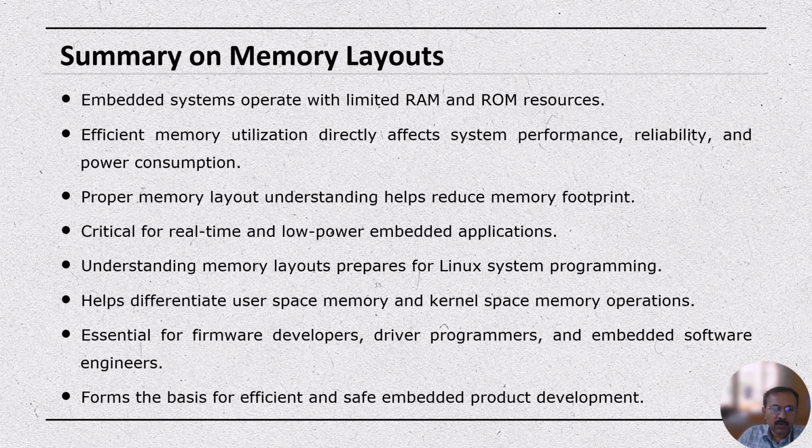It also reduces the memory footprint. What is the footprint? The footprint refers to the amount of RAM and ROM we use for an embedded application. That defines your memory footprint, and it is significantly reduced when you use a proper memory layout. This is highly critical for real-time, low-power embedded applications, because embedded systems are highly resource constrained.